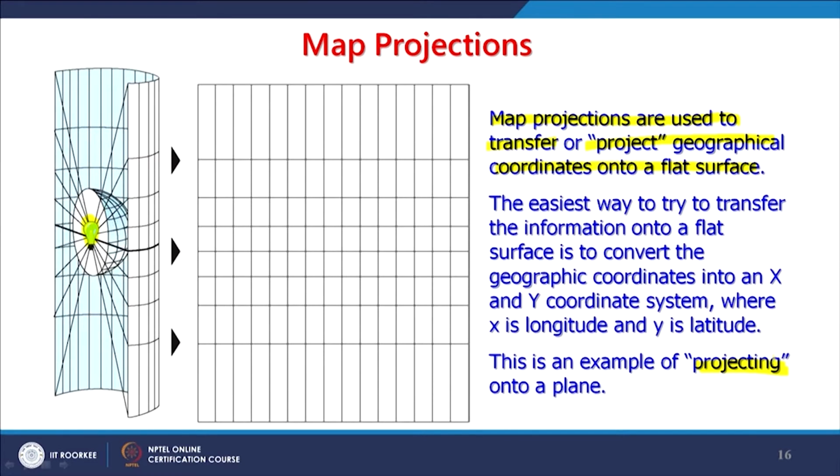For India, if we project in the UTM projection, we get very accurate measurements. So, initially you can keep your maps in XY coordinates or in DD, but whenever you go for measurements, you can temporarily convert to a map projection like UTM, do the measurements and then come back for other analysis.